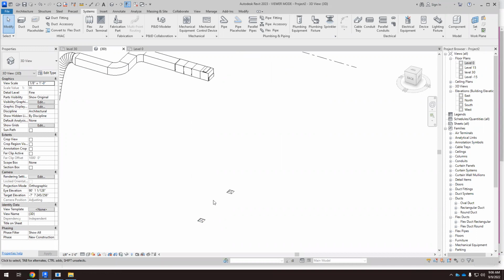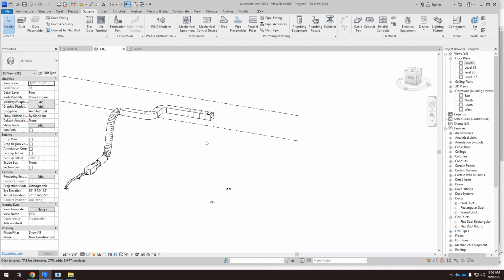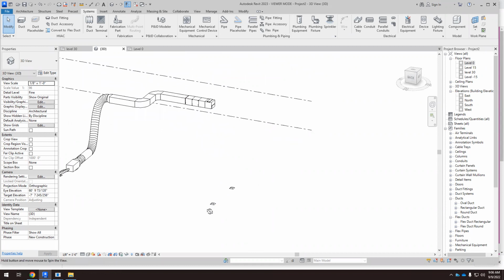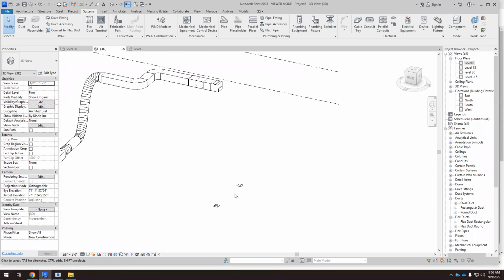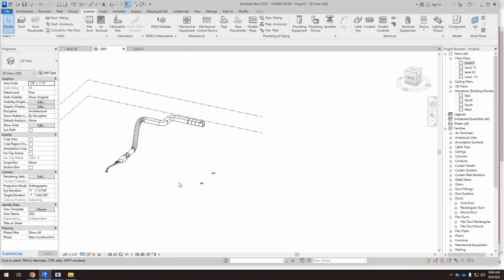So if I have the air handling unit here, and I have the diffusers there, minimizing the ductwork means that we place a horizontal duct here, then go vertical, and then do this. Okay, so now we're going to design this layout, minimizing the ductwork.